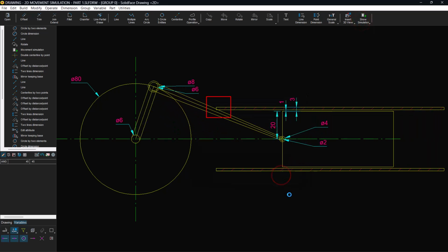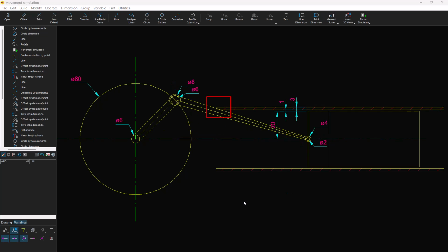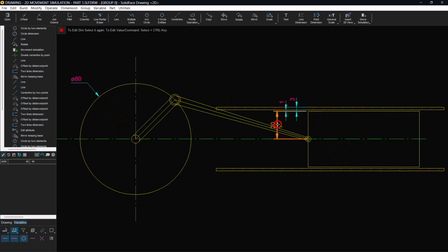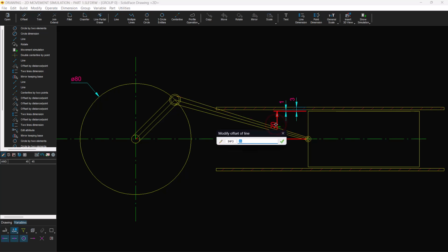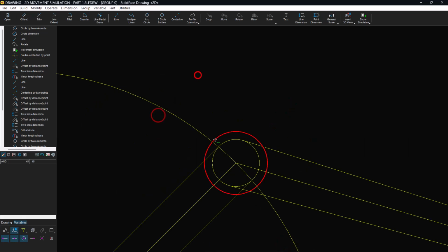Note that a collision has occurred between the connecting rod and the piston guide. Edit the piston offset, changing the piston offset to 23. Add a fill with color to the construction of the connecting rod and piston. Select the circle and the tangent lines, and use the trim command to separate them. Erase the internal lines. Select and delete the lines to create a contour.